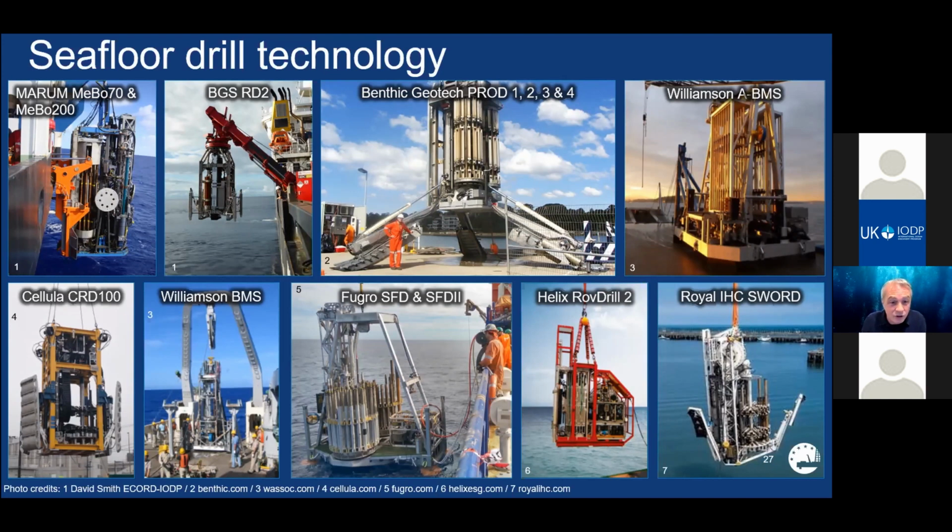This slide illustrates the general size of these rigs. Some rigs like the BGS Rock Drill 2 are quite compact and can fit through moon pools, but others can be a lot bigger than you think. That's important because to use these seafloor drills on research vessels, the vessels need to have the correct deployment equipment and A-frames that are large enough to carry the drills. Also, many of these drills are simply too big to fit through a moon pool, and therefore they need to be deployed either over the stern or over the side.